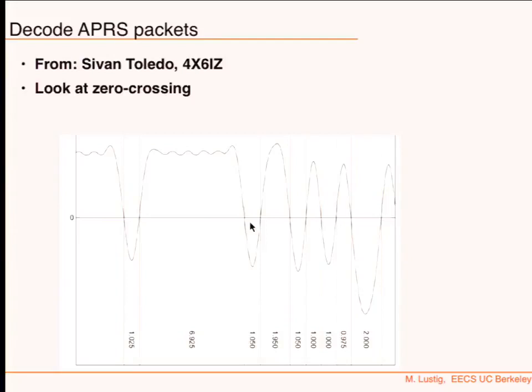The one thing that it solves is the synchronization problem, because this is self-synchronizing. First of all, we allow for errors. For example, if you know there should be a bit 0 over a 1 bit transition, we're going to accept it as a 0 even though it goes all the way to almost 1.5. So it is resilient in that sense to timing error. Any timing error on your transmitter, this actually deals with it. So it's a robust method for timing detection too. It allows for some wiggle in terms of timing.